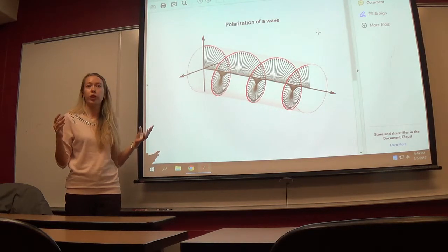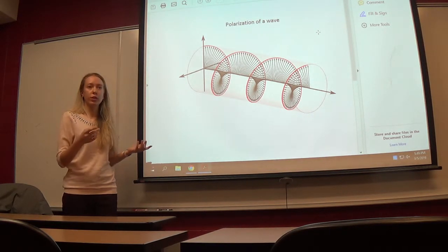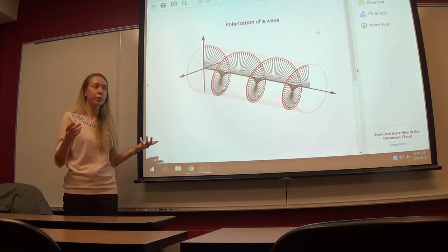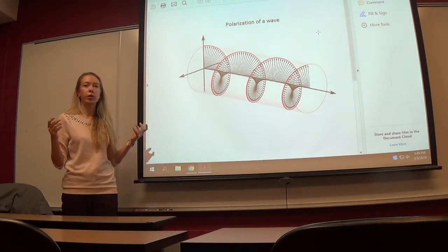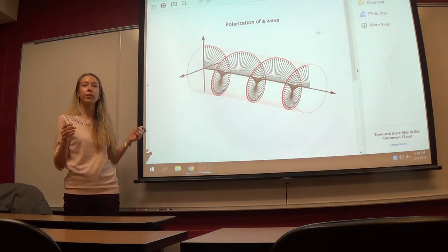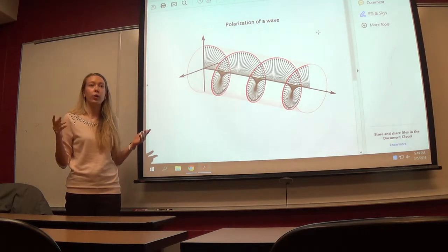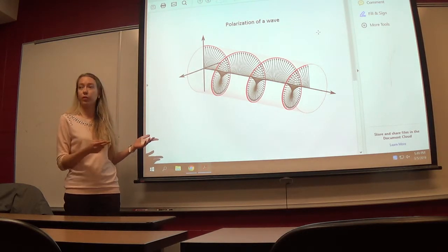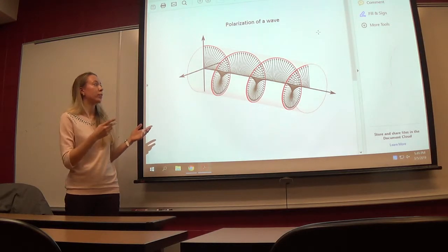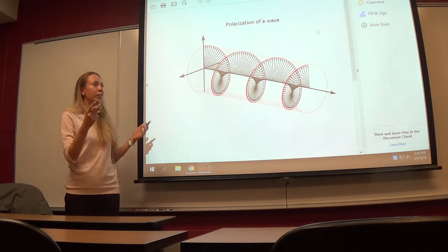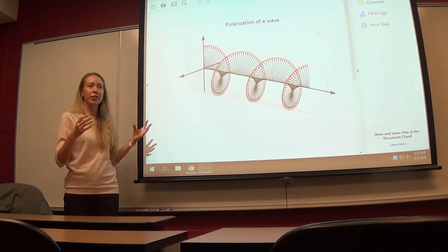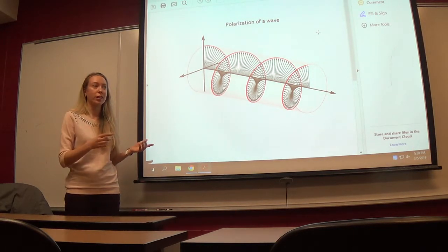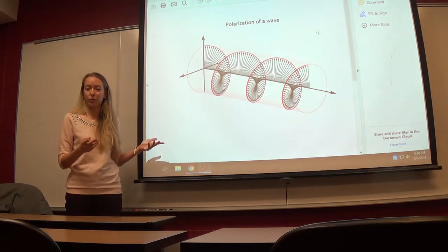Imagine you have a communication system with two antennas. The first one is transmitting some signal, the second one is receiving. To have an efficient communication, those antennas should have the same polarization. Otherwise, a lot of the signal power will be lost, and the system will not be efficient. So when you are designing an antenna, or if someone asks you to build a new antenna to existing communication system, the first question you need to ask and answer is what kind of polarization should be used.